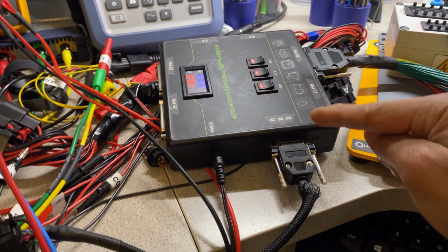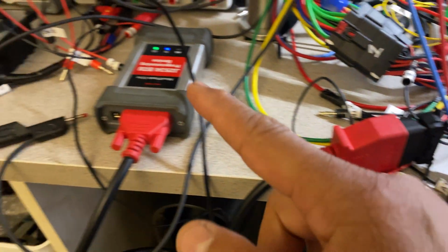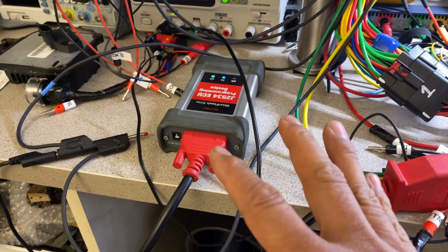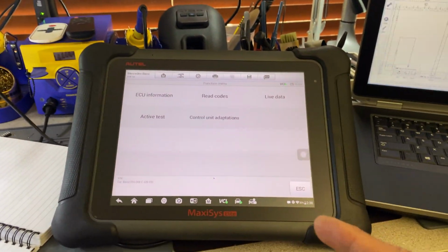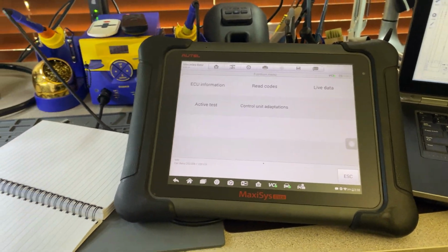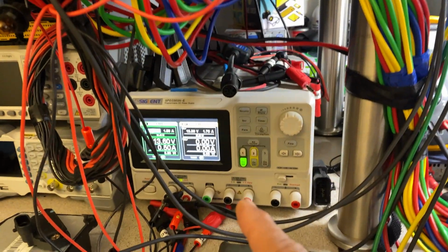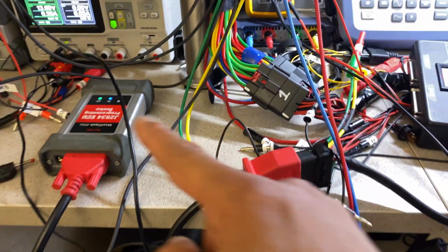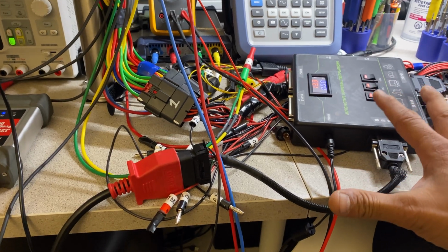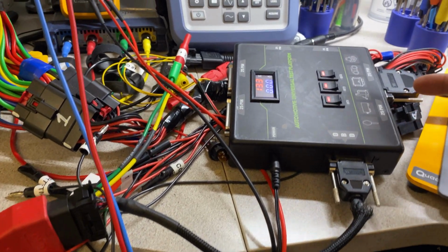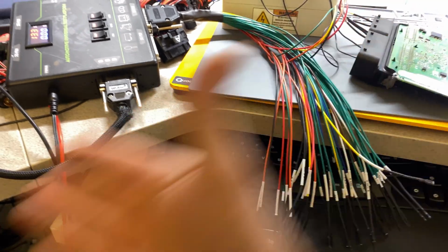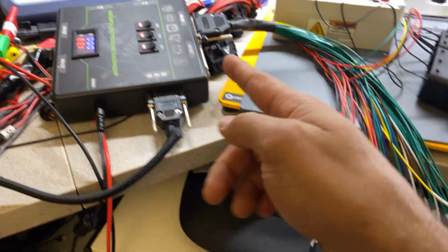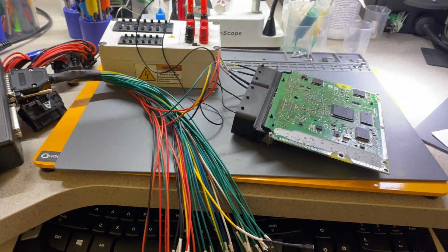It's very handy. You have an OBD2 connector, which I have the OTL connected to, the J2534 pass-through, which also works as a wireless BCI onto my OTL Elite, which I'm using for this. I'm using my power supply in here. I just got powers and ground, which is also supplied to this box with this cable, and then I can connect the 25 pin. I have like 4 different harnesses, with plenty of powers and grounds, and all the cables for the OBD port that I can connect the computers to. All right, so this is a very fast way to show you.